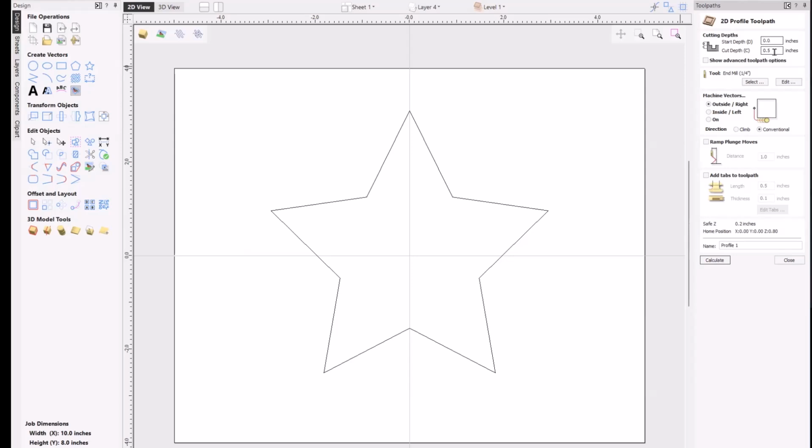In this case, I am cutting it a 1/2 inch deep, and if we look way down here in the lower left, we see that material thickness is a 1/2 inch thick. So I'm using a 1/2 inch thick piece of material, which means I'm going to be cutting this through the material. Now, most people find it's handy to add a little bit extra to that, either 10 thousandths or even 20 thousandths. If you're running a spoil board on your table and you're not cutting right on top of your T-track, then adding a little extra guarantees that the bit goes all the way through the material.